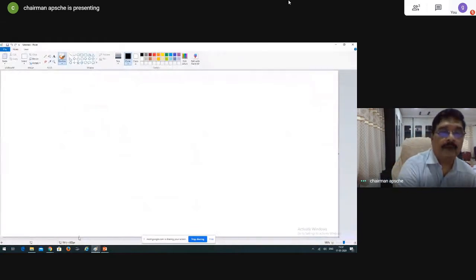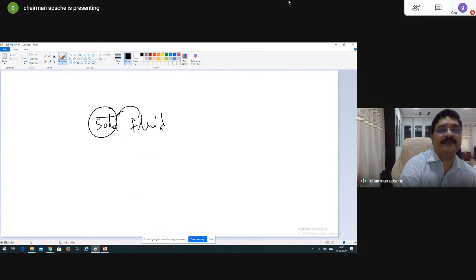Now, for the Biot number, you remember those lumped bodies, I said this is a solid, this is a fluid. Initially it was conduction inside the solid and therefore convection outside the solid, so we drew two thermal resistances. This was a conduction resistance.